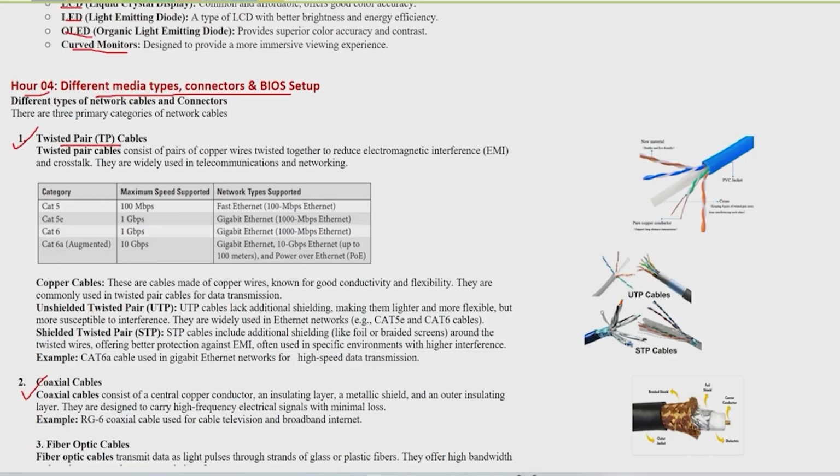Yeah, LAN cables. For example, when I am making a lab of 10 computers, I need to run 10 cables to the switch. There is a cabinet for the switch, and you want to run 10 cables. But sometimes, if engineers don't know, they will run the electricity also in the same duct with the network cables. Then they will say that there is a problem in the communication. Why? Because these electrical cables are now causing problems.